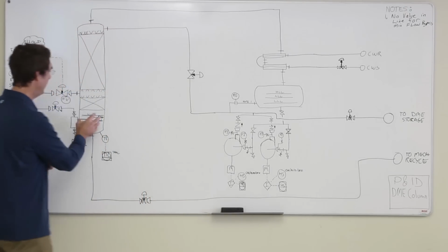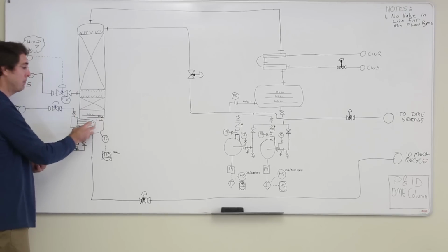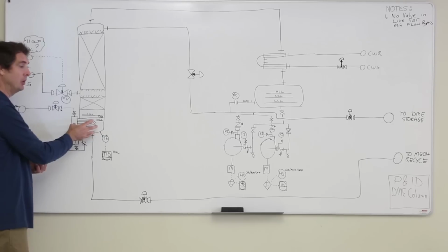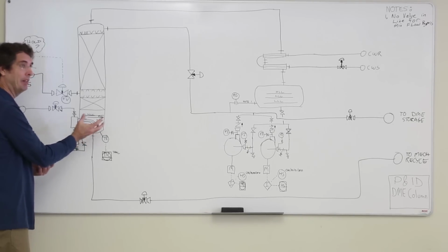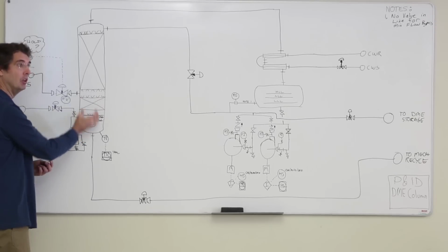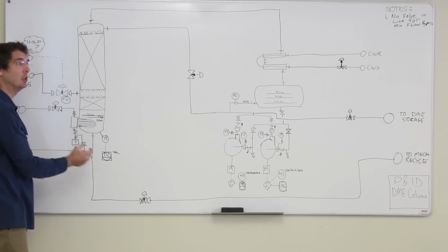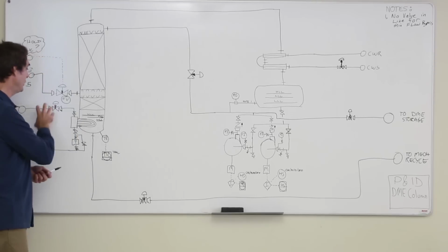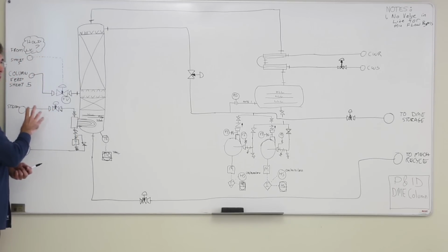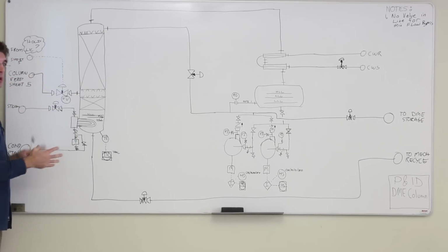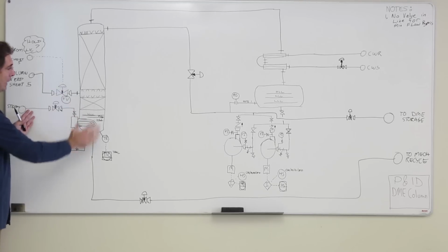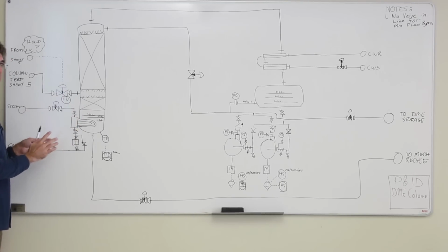In the long term, the response is that boiling this harder will drop the liquid level, but the short-term response might be what they call an inverse response. It might actually cause our measurement of level to look like it's going the wrong way, which will open the steam control valve more and more and more and more. So it's kind of working backwards. You can build a control system that avoids that.